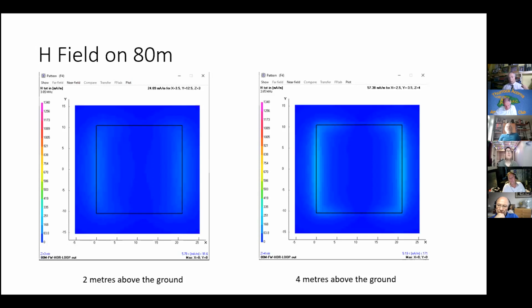It was a frequency dependent limit below 10 megahertz. So their calculation isn't exactly the same as ours, but in most cases, ICNIRP 98 was more conservative than ICNIRP 2020. So you can still use their calculations if you know what you're doing.